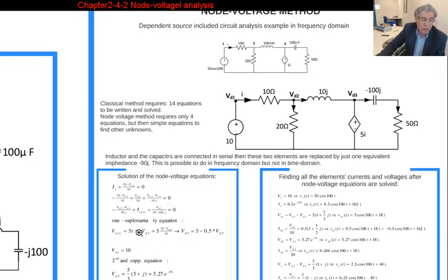We've got to transform it into a supplementary equation by replacing all the variables here with the variables that I would like to see, meaning VD1, VD2, VD3. So 5 times, the current controlled voltage source voltage, which is the voltage of this element in terms of node voltages, is VD3.